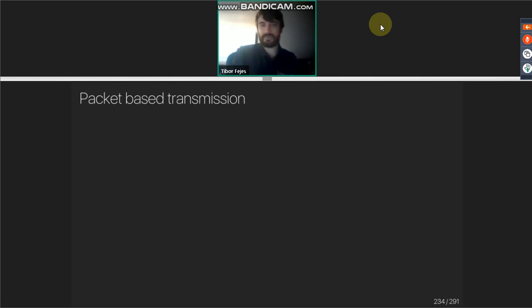So the key difference between HDBaseT and HDMI with TMDS is that whereas HDMI and TMDS is sending the data as a raw stream of bits, HDBaseT is packaged up into discrete packets. Instead of having dedicated wire pairs, we have dedicated packet types.